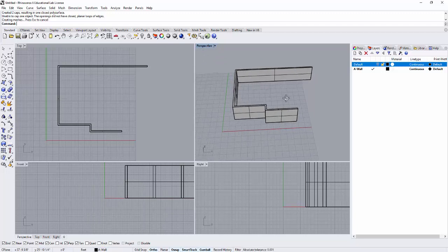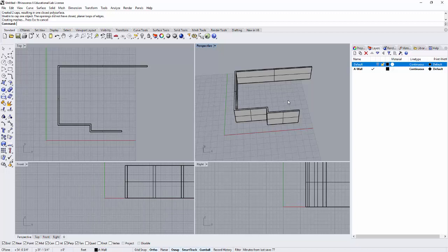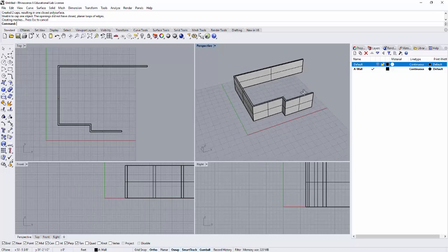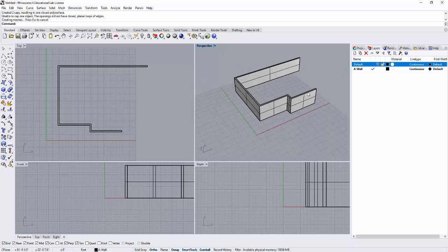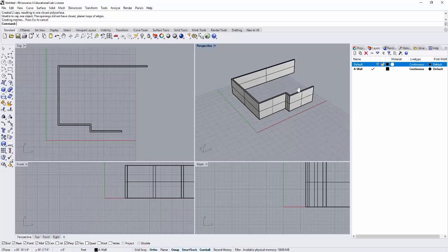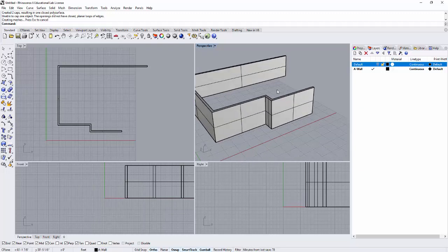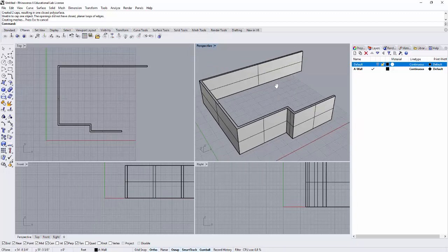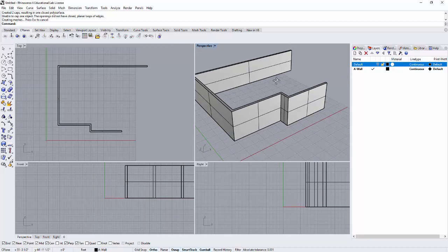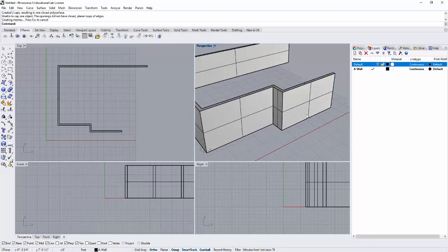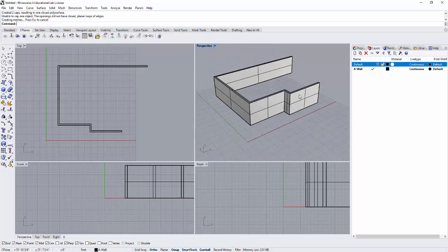So two more quick things to run through, and that is establishing different working planes and Boolean objects. And that's going to get you sort of really the basic tools that you need to really start putting some things together quickly in Rhino. So setting construction planes is the second tab over from the standard tab. And this is a really useful feature, and this is something you're going to reference often as you're doing work in 3D. So for this, if I want to create an opening here on this wall that represents the entry to my design,